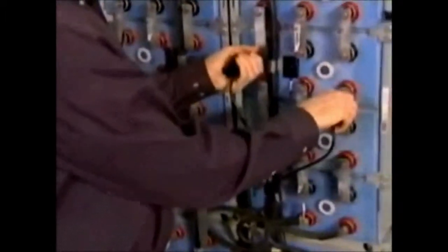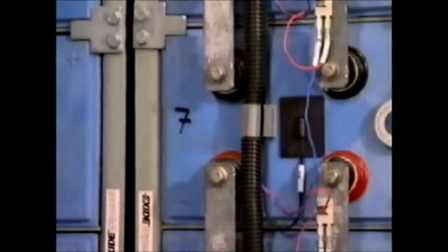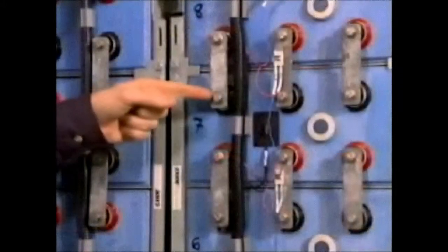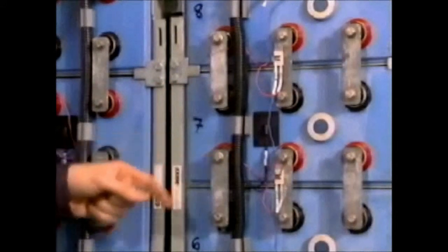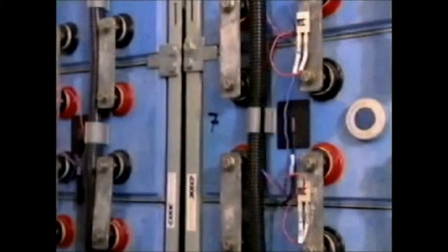Let's start with the DuraProbes. It's important to understand where the best contact points are. One contact point to avoid is the stainless steel hardware. Stainless steel gives lower test readings, possibly even a false failure indication. Instead, make sure the probe touches directly onto the lead post. This registers the highest measurement and the most uniform information.